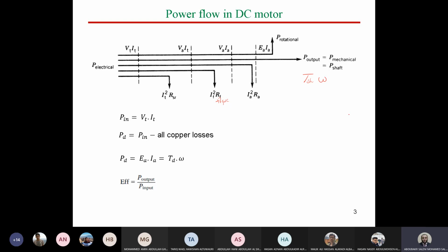So we can say that this is the equivalent circuit, for instance, for the separately excited DC motor. We can assume that we have brushes like that here. So this is V terminal. Here we have the armature current. We have RA, we have LA, we have here EA. So we can consider that the element which represents the gained power is nothing but EA multiplied by IA, which is the developed power here, okay? However, there is no resistance representing the gained power in a DC motor.